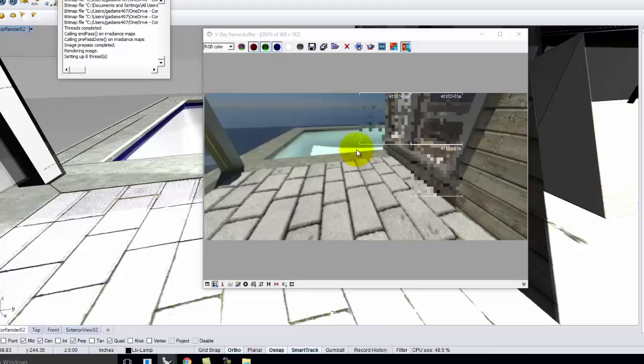Okay, so there you can see it much better. The light bottom pool has a different look as part of this. All right? Okay, so thanks for bearing with me. I think that a lot of people will find that water pool thing useful. If we wanted more ripples on the surface, we can adjust the bump map, or excuse me, the displacement map on the material, and we get more waves on the surface. So it depends on what your end goal is. All right?